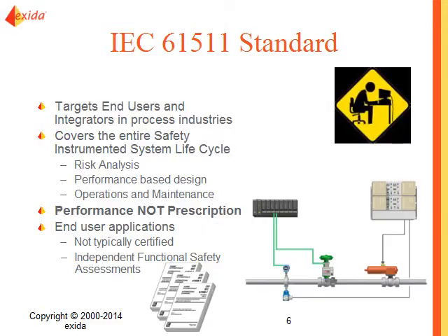In terms of the IEC 61511 standard, this is targeted at end users and integrators in the process industries. It covers the entire safety life cycle for an instrumented system. And there's effectively three phases for that. There's the first phase, which is where you do your risk analysis. The second phase, which is performance-based design.